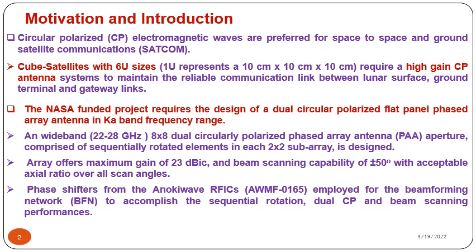Here, phase shifters from Anokiwave RFICs are employed for the beamforming network, which help us to accomplish the sequential rotation, or in other words, the phase required for sequentially rotated elements. And also, it provides the phase shift required for dual CP as well as beam scanning performance.